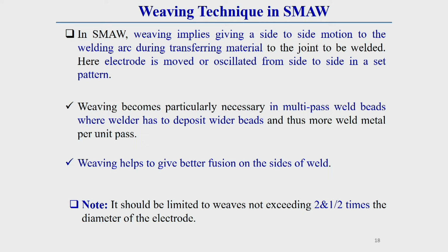This weaving operation is required where more material must be deposited and a wider weld bead shape is needed, especially for multi-pass welds or thicker sections.